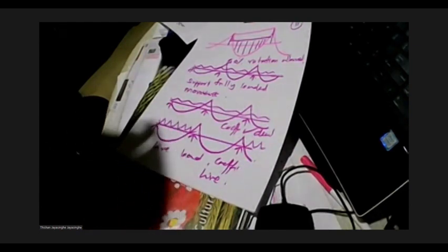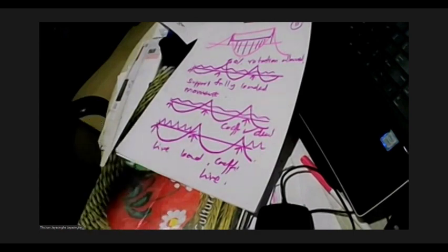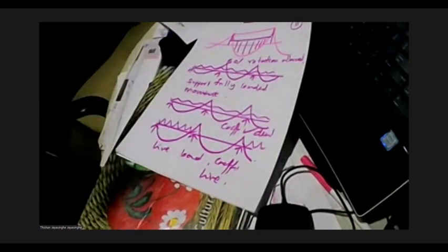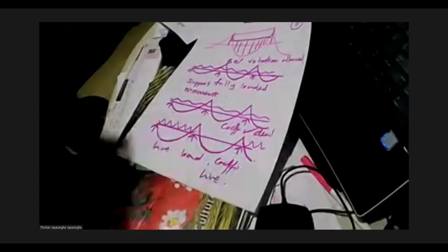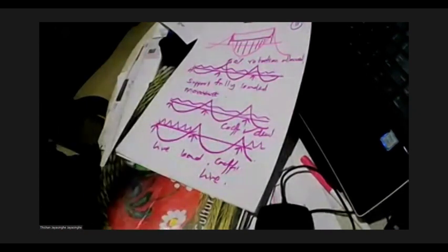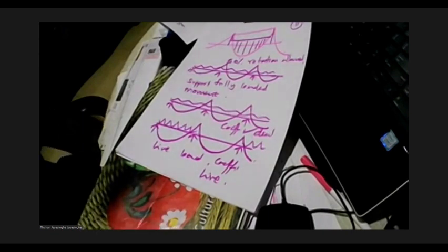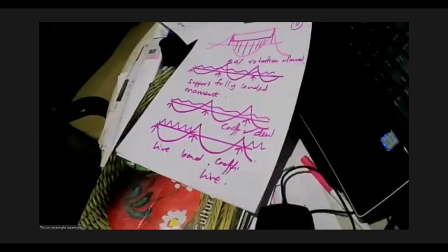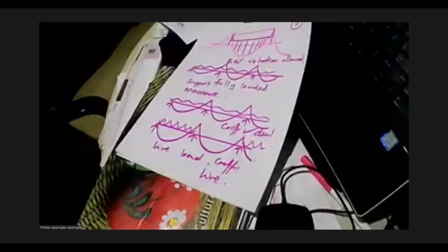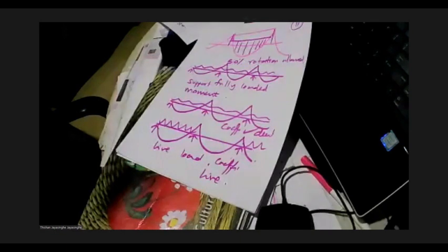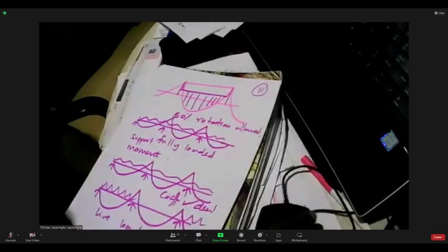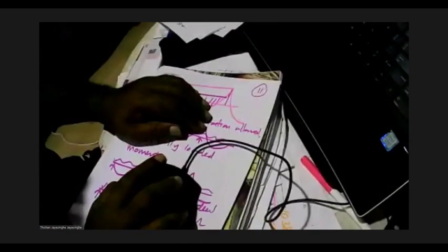For dead loads, we don't have to consider pattern loading. For the support, we don't have to consider pattern loading because the maximum bending moment over the support occurs when all the spans are loaded fully. Can you understand this, Bhashita? Right. So, to find, I'll share the screen.